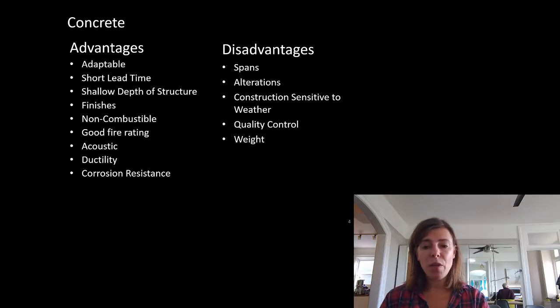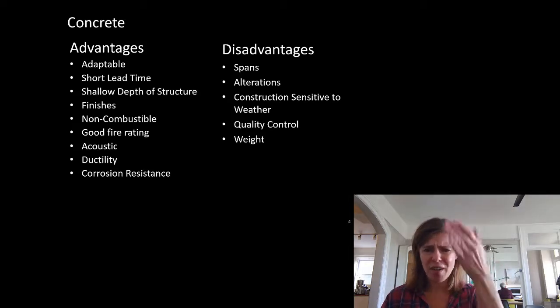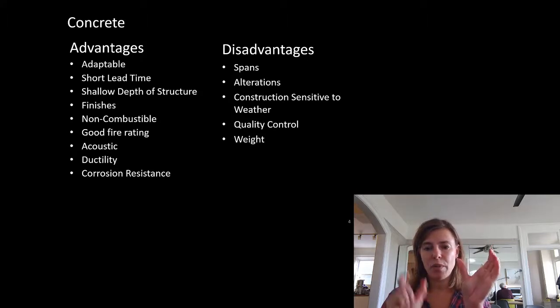So I wrote yet another memo that pointed out that, when we're working between metric and imperial, we might say that the wall is 203 millimeters thick, meaning 8 inches, or 200 millimeters, which when we switch to imperial, we often just round off that 3 millimeters. That door opening was less of a change than the difference in two engineers doing the calculations using 200 millimeters and 203 millimeters. So when I wrote that memo, the building department was okay to say, all right, put your door in and leave us alone.